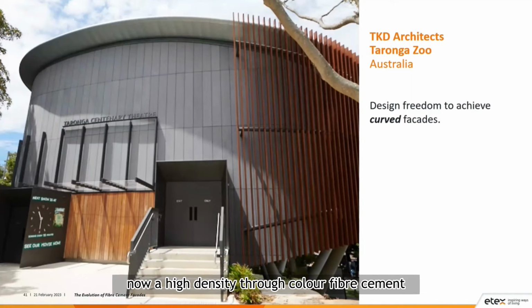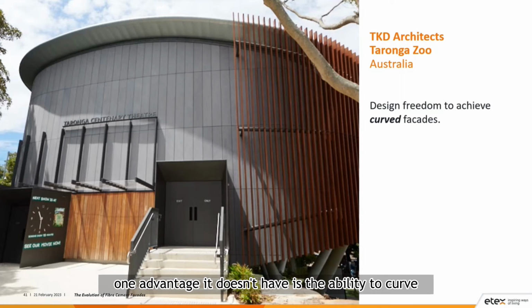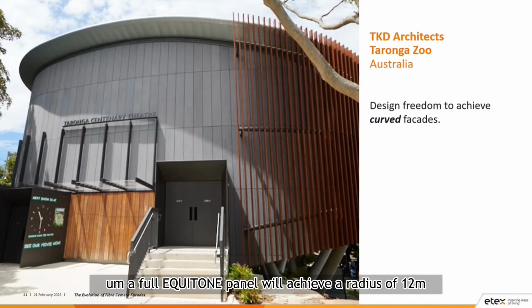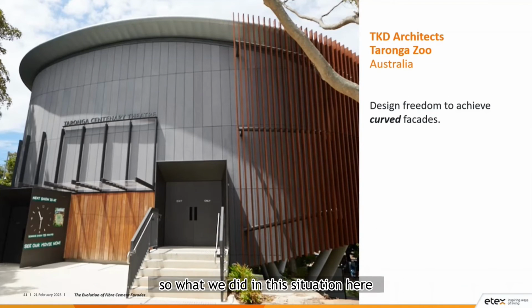Now, a high density through color fiber cement contains a lot of advantages over a painted medium density or a compressed fiber cement. One advantage it doesn't have is the ability to curve. Because it's a lot harder panel, it's also harder to curve. So this project in Australia, they wanted a curved facade. A full EQUITONE panel will achieve a radius of 12 meters. This project here had a radius of 4 meters. So what we did in this situation here is we had to create 400 millimeter strips to fasten it around the building in order to create that curved facade for the Taronga Zoo project.